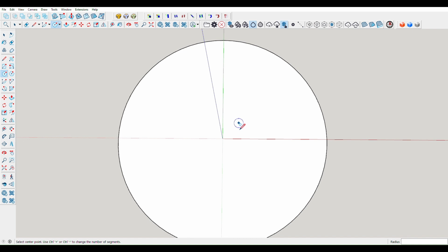First of all, we start by drawing a line by pressing the L key. Here we go, a straight up line, and I tend to do this by eye. So we're going to create a circle here, nearly to the outside edge, but not quite. Then, because we're making 6 petals, I'm going to rotate this by pressing the Q key and pressing Control to make a copy of this.